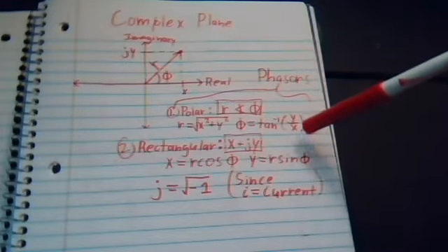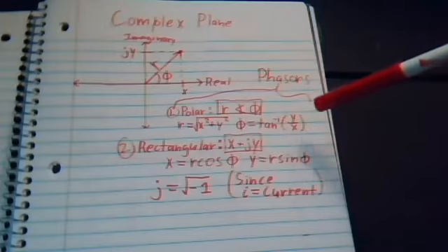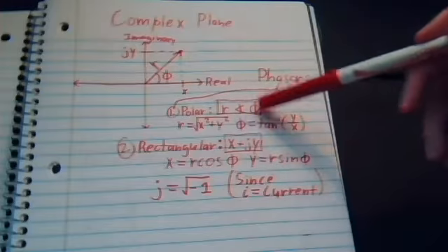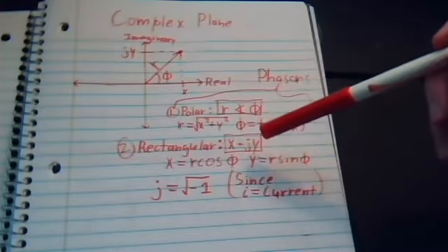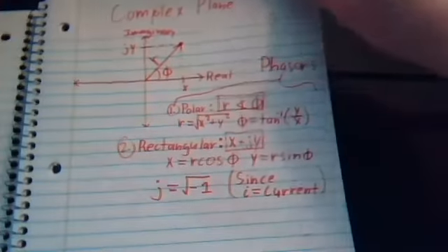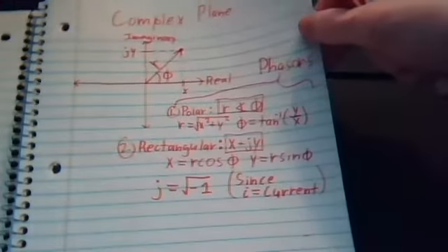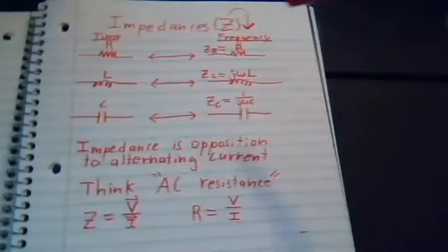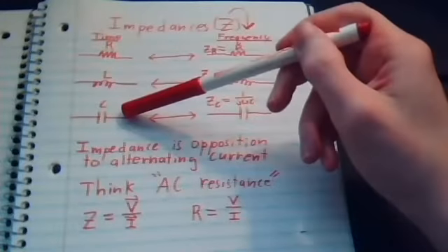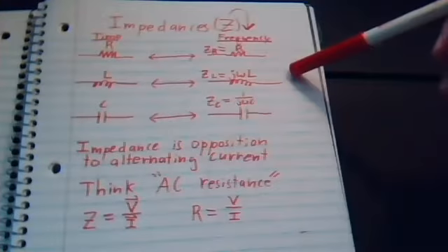So we're able to freely convert back and forth between these two using these two sets of formulas. The only time we have to do this is when we're manually doing phasor math ourselves. If we're trying to add polar numbers, we actually can't. We've got to put those in rectangular using these equations first. And so that's how we represent our sinusoids. We put them into phasors to get them into the frequency domain. But we also have to convert our components. So R, L, and C in the time domain are going to have to come over to the frequency domain.